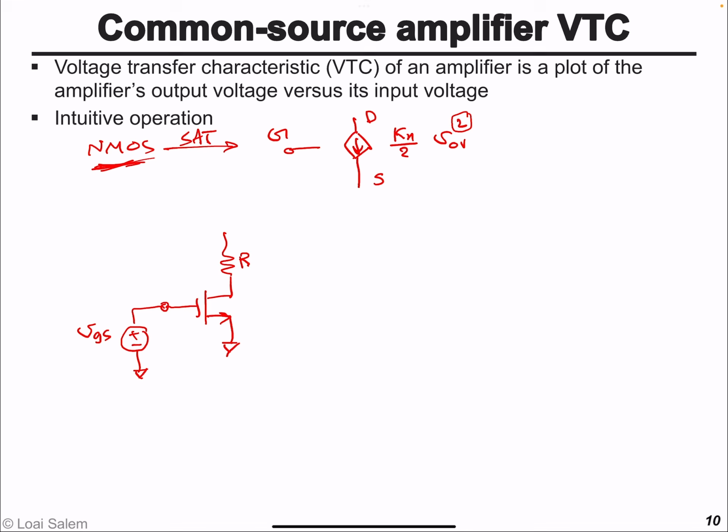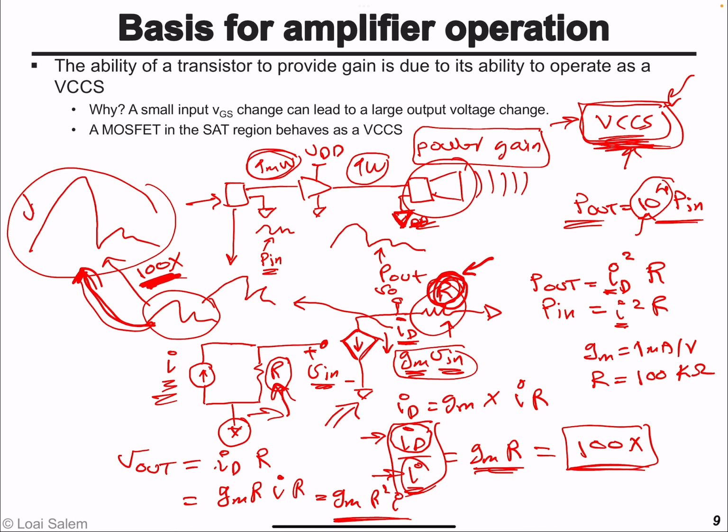And then we're going to connect this resistor to a supply voltage to provide power, because as I mentioned, the voltage controlled current source essentially is not magically generating the power externally. The extra power that's in the output is coming from the input DC supply. So the total input power that's coming from the microphone plus the DC supply is equal to the output power, assuming lossless operation.